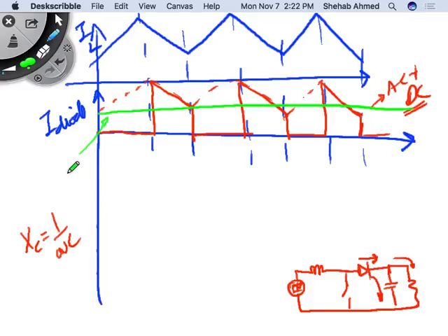No. Exactly. It's a diode average current. What is diode average current? What did we say? It's 1 minus D times the average value of inductor current. Right? Remember, inductor current is coming through here. It's chopped up between these two. That's it. IL average is coming here. It's divided between switch average current and diode average current.